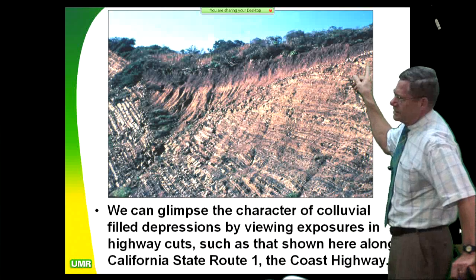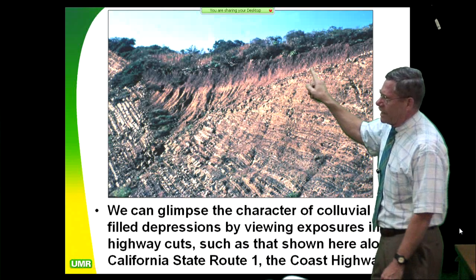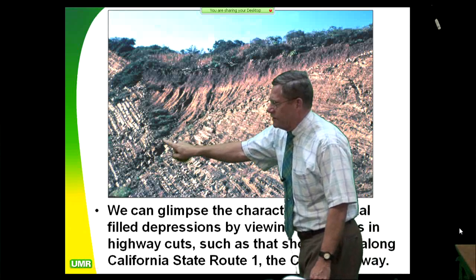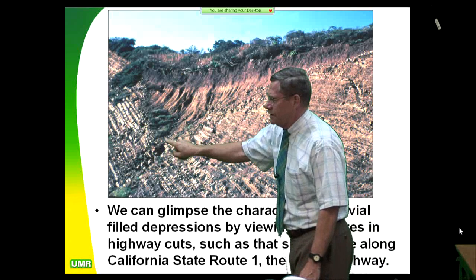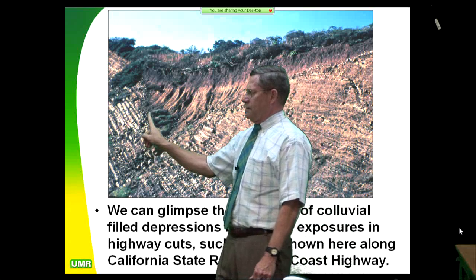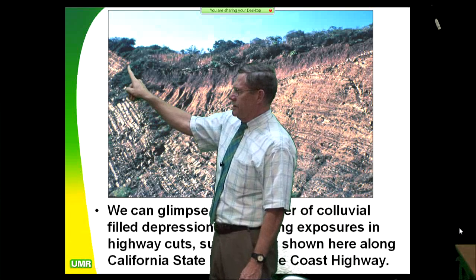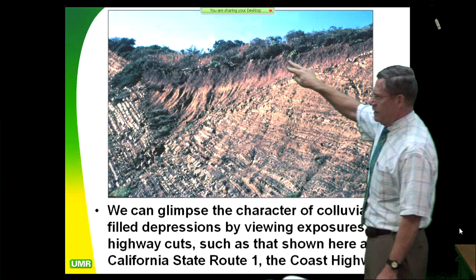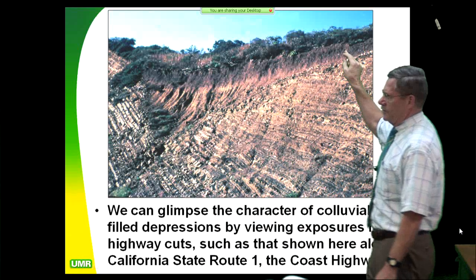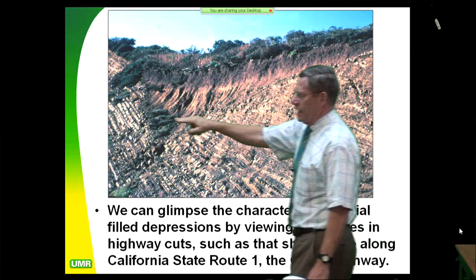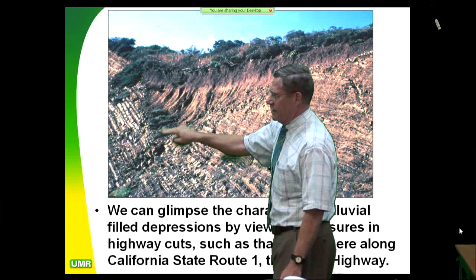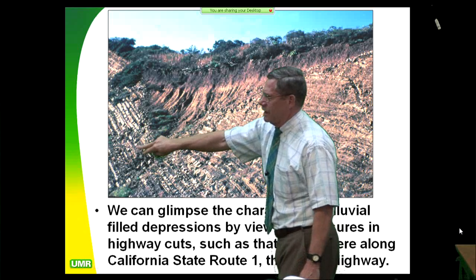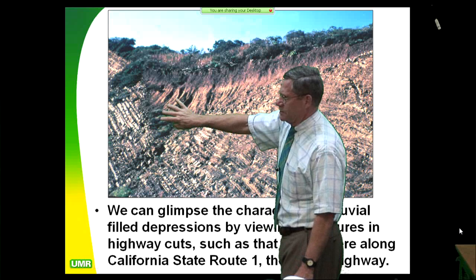Now what you see here is the bedrock colluvium contact. Watch this, it comes down, down, down, dives right here, 17 feet below the ground surface, and then comes back up. I've got a very well-developed argillic B horizon right there, a little bit immature, a nice A horizon, and I've got all kinds of water-loving plants right here. Can't imagine why. That's where the seepage is. There's a permeability contrast right here between this soil-type stuff.